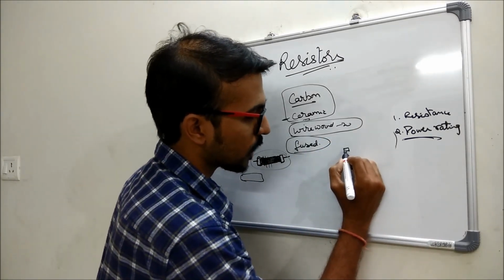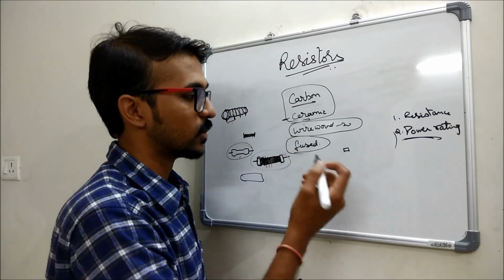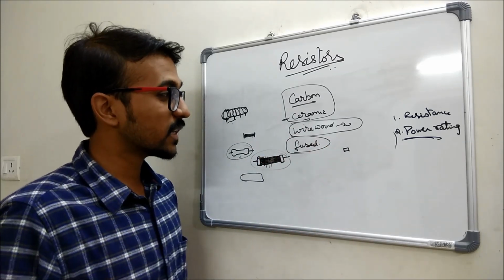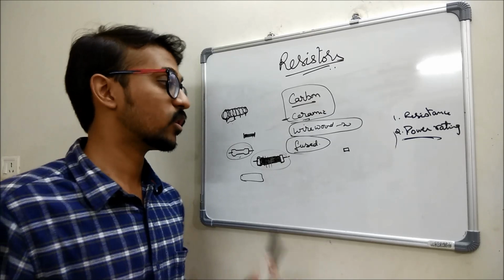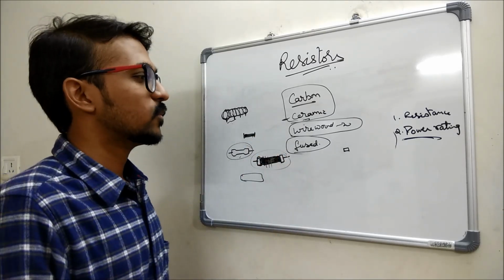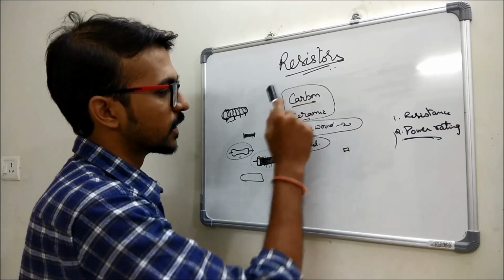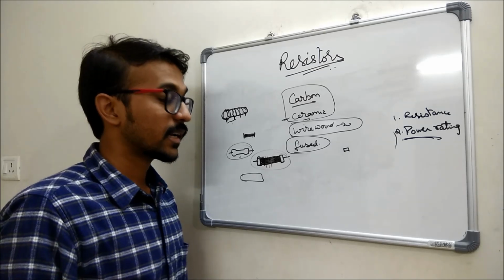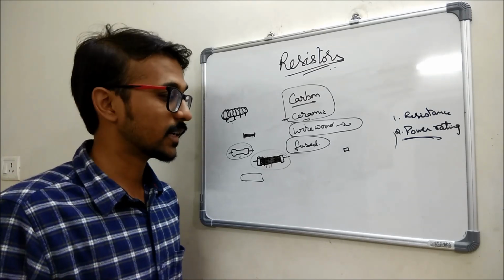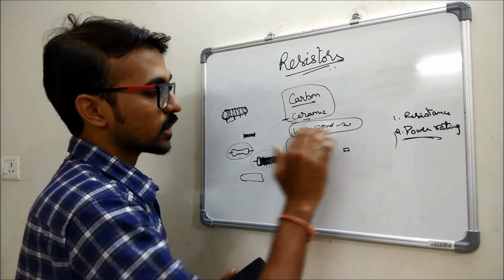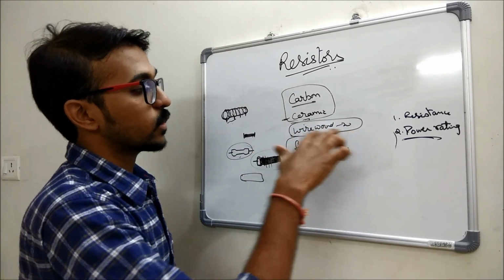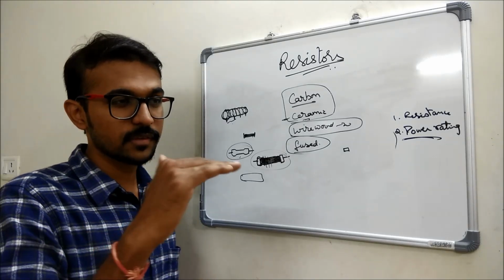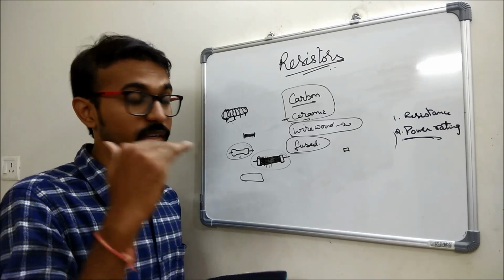These will be very small, and the coating will almost be the same on them. And this is mostly the construction of resistors. So based on your need, based on the value, based on the power which you are going for, you can choose different types of resistors here. And mostly I use ceramic, carbon and wire wound. Fused I have never used much in my circuits, but I have a few lying around on my table, and I mostly don't prefer them. But wire wound, on the other hand, yes, I use them. And the advantage of wire wound is that they usually heat up and don't burn out so fast, even if the power used is on the edge of the rating of the resistor.